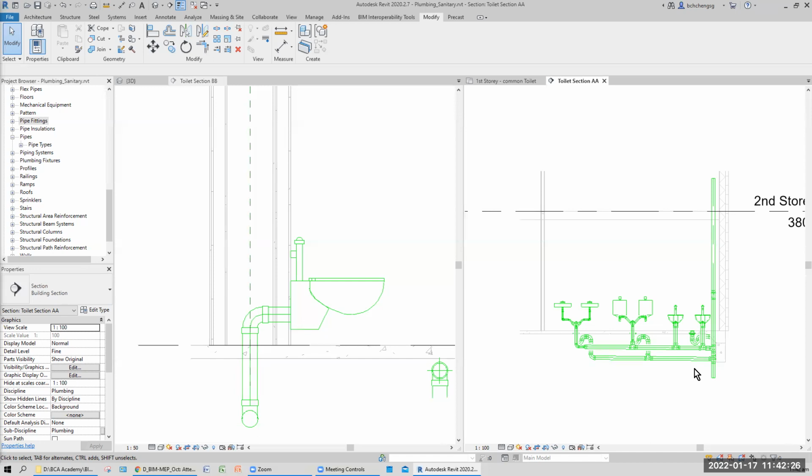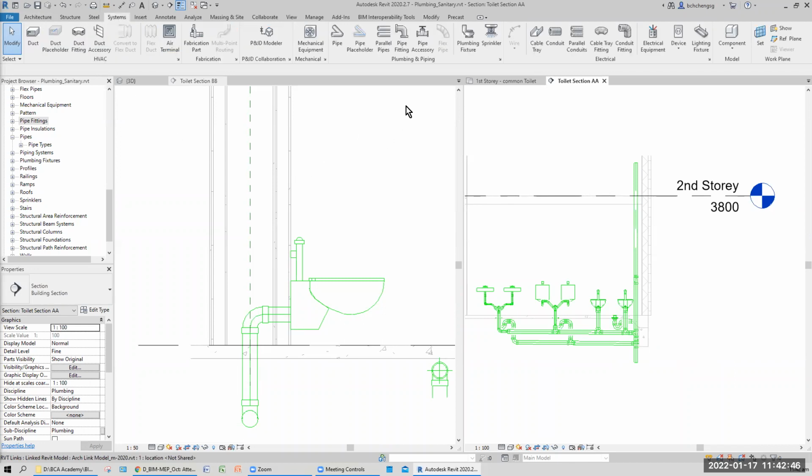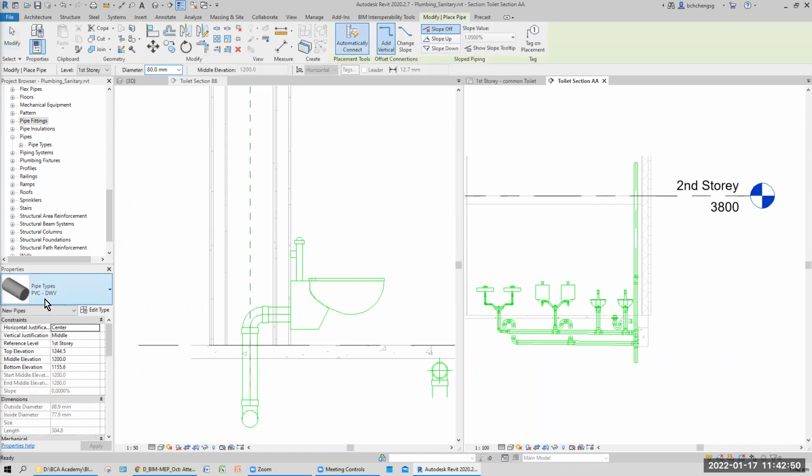So from here, supply to the building, the diameter is a 50 mm pipe. Okay, to the building only, not into your household, to your shower tap, not yet. So from what you see here, you go to sketch. So go to system. Now the pipe here, as I said, the material must be PVC.